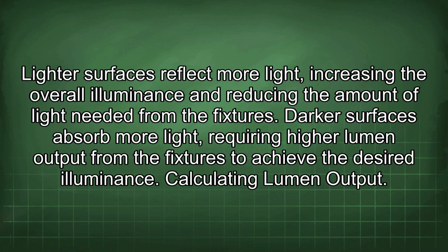Lighter surfaces reflect more light, increasing the overall illuminance and reducing the amount of light needed from the fixtures. Darker surfaces absorb more light, requiring higher lumen output from the fixtures to achieve the desired illuminance.